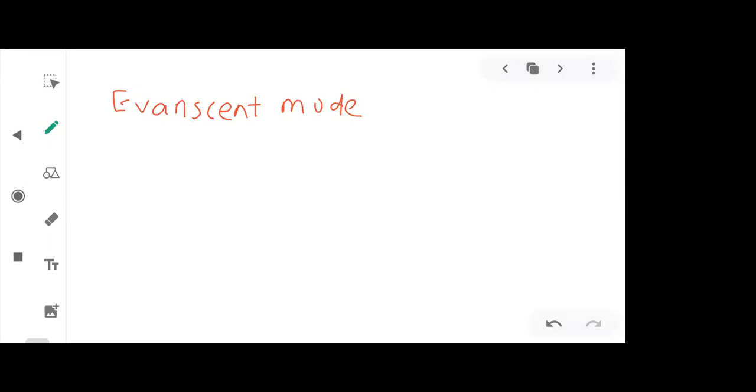So we have got the idea about what is the dominant mode, what is the degenerate mode, and what is the evanescent mode, and a list of formulas with the help of which we can calculate cutoff frequency, then phase velocity inside a guide, group velocity inside a guide, then the characteristic impedance offered by a waveguide. But remember that there is no fixed characteristic impedance of a waveguide. That is the issue with the waveguide. Nothing is fixed for it. At different locations, the characteristic impedance is going to be different.